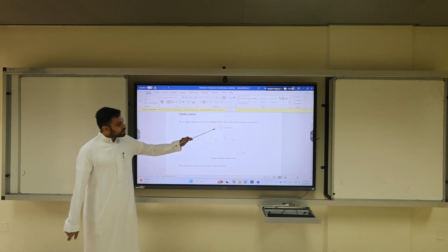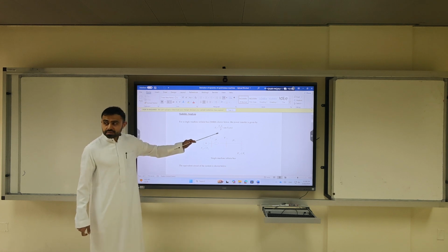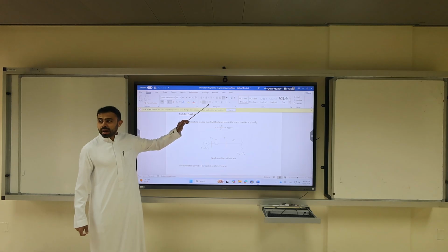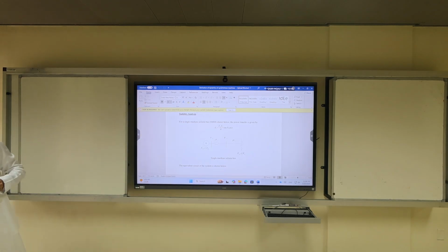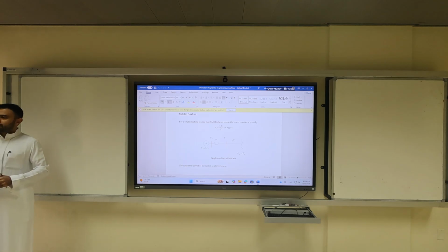And we noticed that if you reduce X, you increase the maximum power that you can transfer at 90 degrees. Will in real life operate at 90 degrees delta? No. But our, let's say, 80 or 75% that we would operate would have a higher power transfer capability.